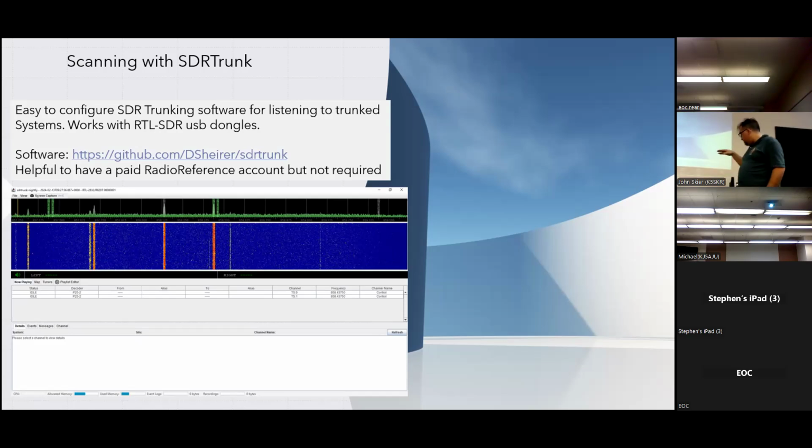When I first got into trunking decoding, it was back in 2005, 2006. I saw this great thing on the web put out by Patriot Waves. It's two RTL SDRs built internally into one package. At the time, the only decoding software for P25 and trunking required two SDRs, because the application was written so that one SDR was dedicated strictly to the control channel, and the second SDR to the talk groups you listen in on.